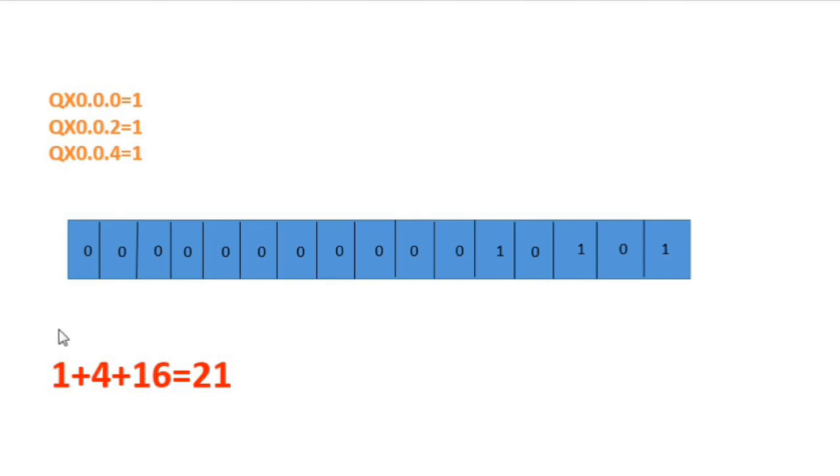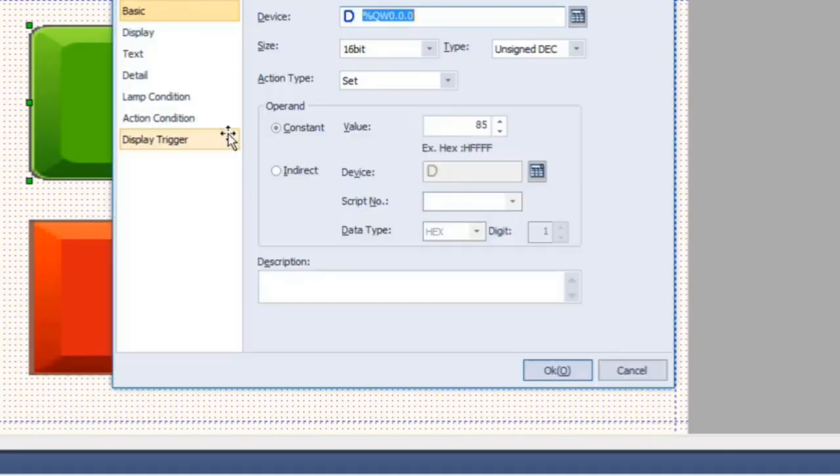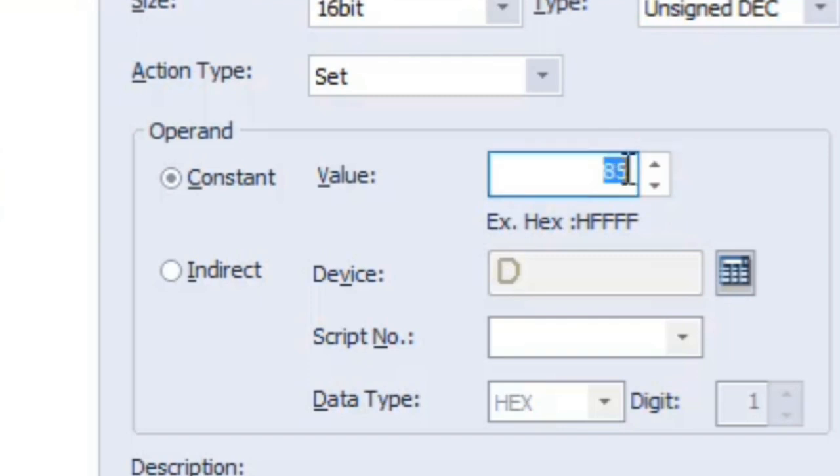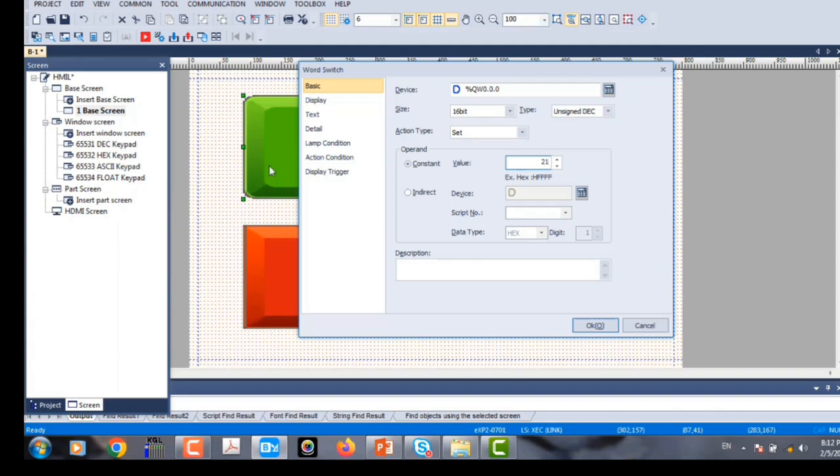and we set the rest of the remaining outputs to 0. Now this is a binary number, and if we convert this binary number into decimal format, it becomes the number 21. So if we go into the XBuilder software environment and look in this fixed value section, if I enter the number 21 here, set its value to 21 and confirm it, and then upload this program to the HMI, basically the exact same program we just did together, then whenever I press this start switch, the Q0, Q2, and Q4 outputs will be activated for us automatically.